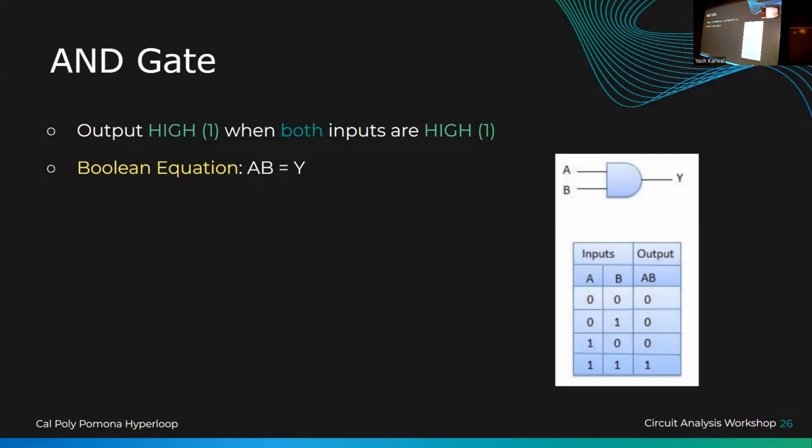So an AND gate has 2 switches, right? Switch 1 and switch 2. In this case, if you turn on switch 1 and switch 2 is turned off, how does this work? The current still won't pass through because switch 2 is open. But if switch 1 is open and switch 2 is closed, in this case too, electricity cannot flow from point A to point B because switch 1 is open.